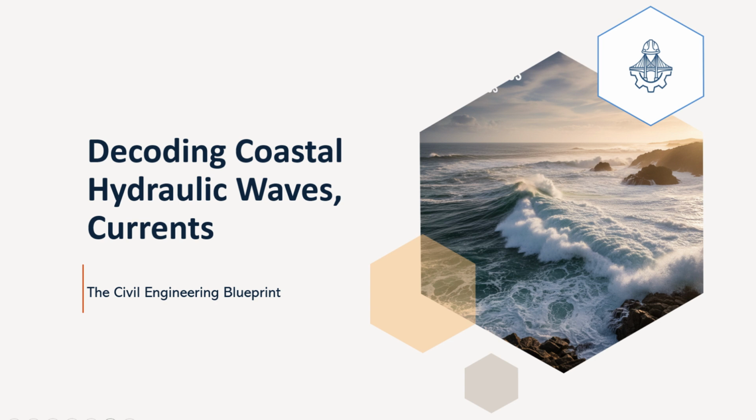Then determine conditions at d equals 8 meters. Find the relative depth d/L0 for this depth, then calculate Cg at 8 meters. Now apply the shoaling relationship. We know H at 10 meters, and we can use this to relate the heights at 10 meters and 8 meters. Dividing these gives the height ratio, using the values derived from wave tables, as in the source example, which effectively calculated Cg directly. Ks at 10 meters is 0.9327 and at 8 meters 0.9768, and the ratio is 0.9883. Note, these numbers represent the ratio Cg0 over Cg. Finally, calculate H at 8 meters. Since H at 10 meters is 1.5 meters, then H equals 1.5 times 0.9883, which is about 1.48 meters.